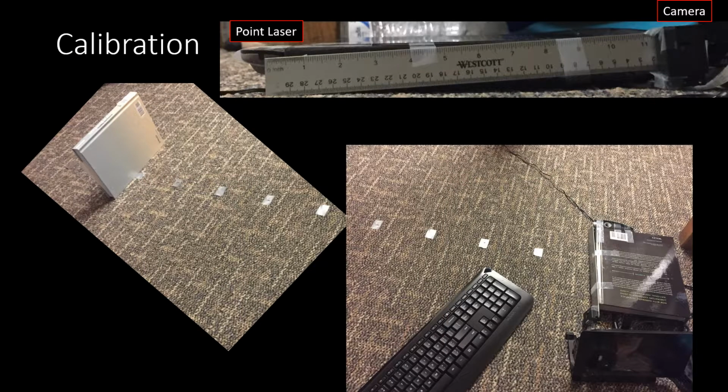The calibration was first conducted as a proof of concept using a point laser and a Pi camera taped to a book 12 inches apart. The setup was placed in a fixed location and 6-inch markings were labeled on the floor for 10 feet in front of the laser. A book was held at each location while a picture was taken.